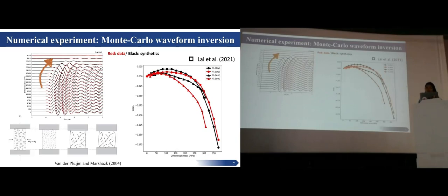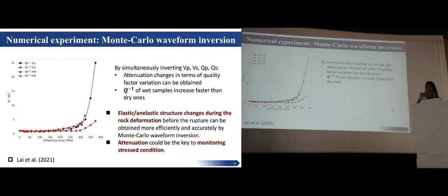And I also plot the evolution of velocity like this. It's related to the figure I mentioned before, the 4 stages. The velocity first goes up a little bit and then drops really quickly when the microcracks happen in the material. And then I also plot the attenuation, the quality factor changes, 1 over Q, which means the higher the 1 over Q, the higher the attenuation.